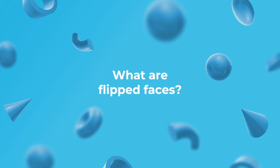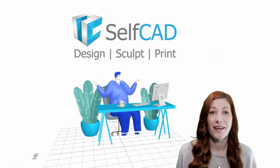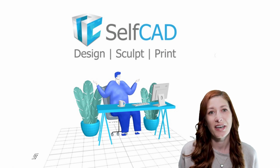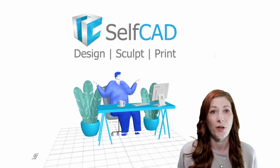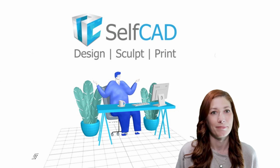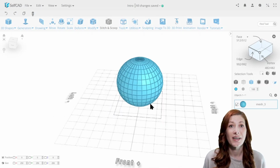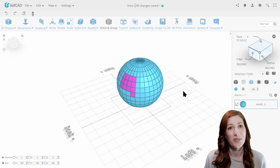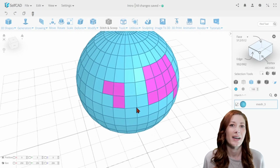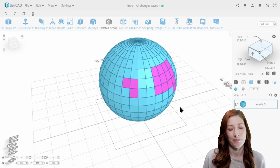What are flipped faces? The second problem we can search for with back face coloring are flipped faces. When we talk about flipped faces, we're talking about a situation where the face normal, or the vector, flips and the inside face points outward. We can similarly spot such issues by inspecting the object from all sides like we did when searching for holes. But in this case, we're not looking for a changed color inside the object, and instead are looking for a changed color on the object's surface.